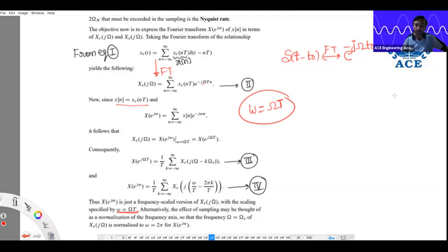That is what I mentioned. In the process of converting analog to digital frequency, as our digital frequency is limited to the minus pi to plus pi range, we are doing normalization of the spectrum, or not? Don't bother about the mathematical expressions. See the sequence of steps. Here we are observing how the sampled CTFT spectrum will appear like the discrete time Fourier transform.